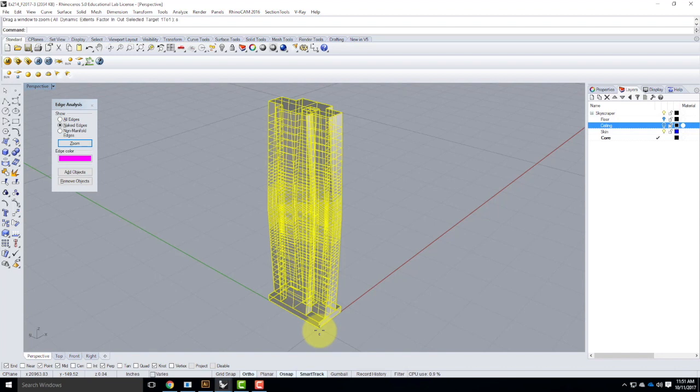This now is at the size that's appropriate for 3D printing, which is great. Unfortunately, the 3D printer doesn't like inches. So we need to convert the scale, or the units of this drawing, not the scale anymore, the units of this drawing, into millimeters, which is what the 3D printer likes. So at this point, we need to switch our